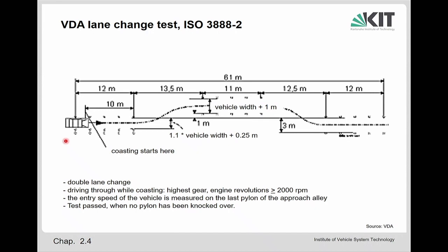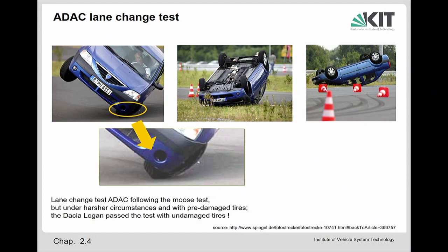What is shown here, for example, if you go through that curve, you can see this is exactly the double lane change curve test with the pylons. So the car has already hit a lot of pylons, and it is going here on the upper left. It's going here into a right-hand curve. You see, it has completely lifted off the inner side of the vehicle.